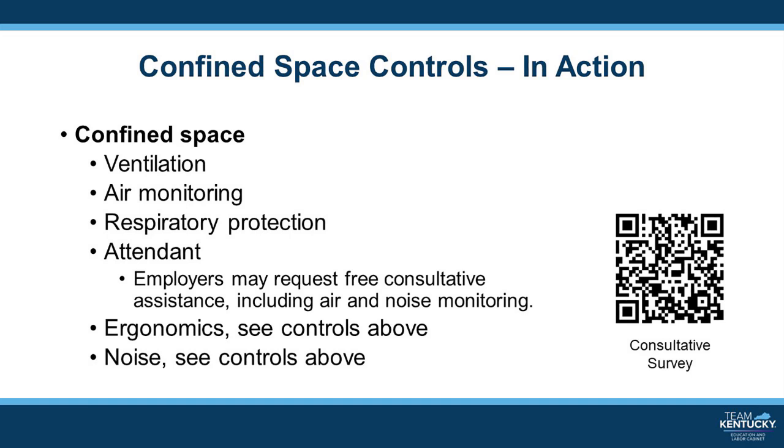In a confined space, there may be a requirement for an attendant to be present who remains outside the confined space and maintains contact with the worker who is inside the space. This is to ensure the safety of the worker in the event of an emergency and an emergency rescue is needed. Each work site and situation could vary.